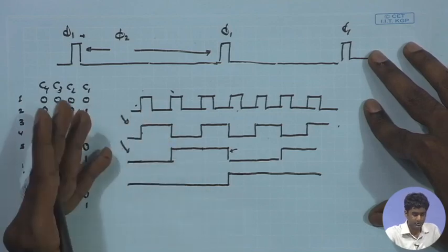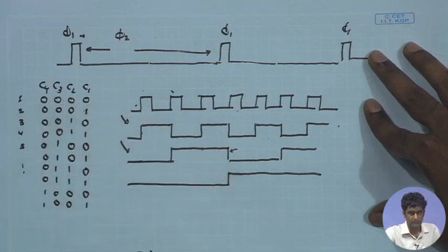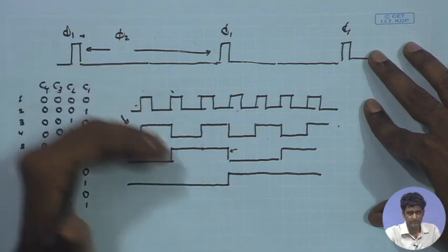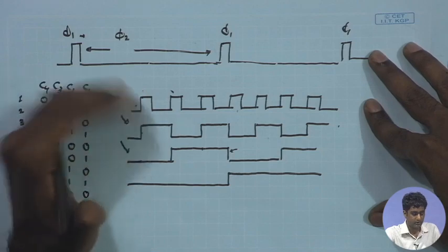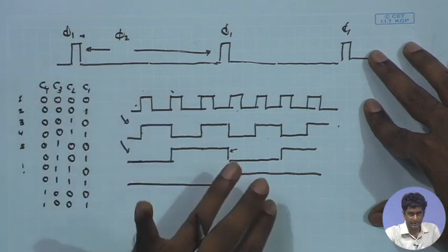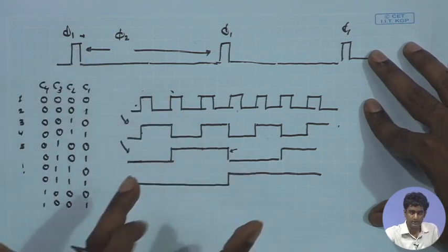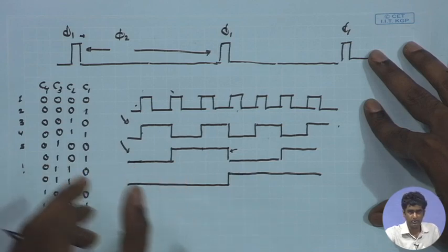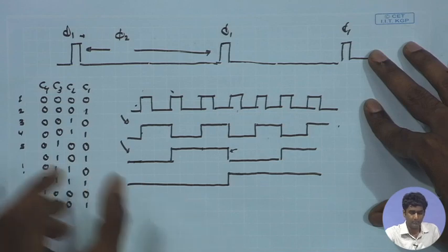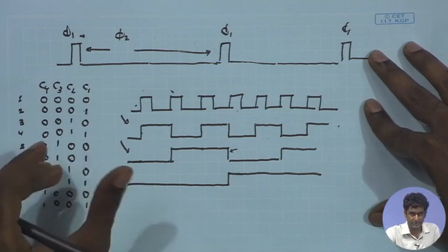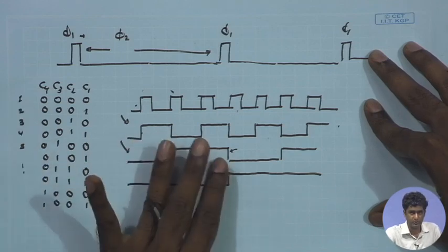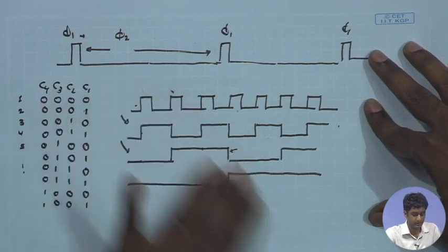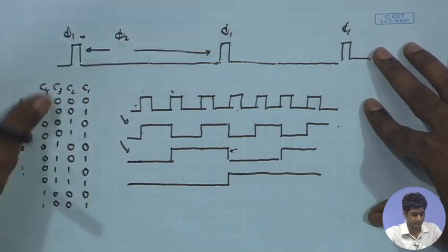Sequential circuits which can give us a clock driven operation can be level sensitive or edge sensitive. So, let us see the definition of level sensitive and edge sensitive blocks, and then look at the definition of a flip flop, which is basically a cascade of two opposite phase level sensitive latches. With the help of that we can see how we are going to construct such a counter which is performing the overall counting operation.